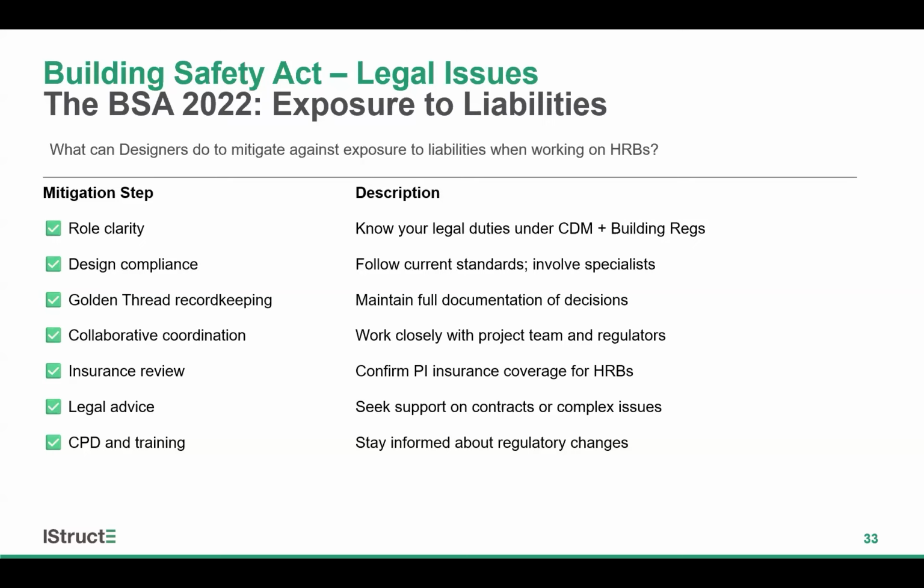With regard to the golden thread, this is required for higher risk buildings, but also good practice generally. But good record keeping is the easiest way to prove your compliance if ever questioned. The biggest issue we see on projects, when considering golden thread or not, is a lack of records. And a lack of records makes it extremely difficult in a dispute situation to either defend or advance claims.